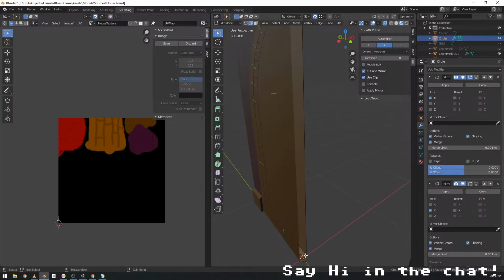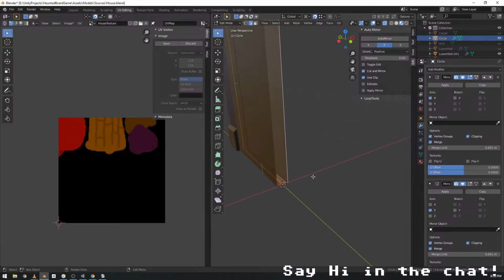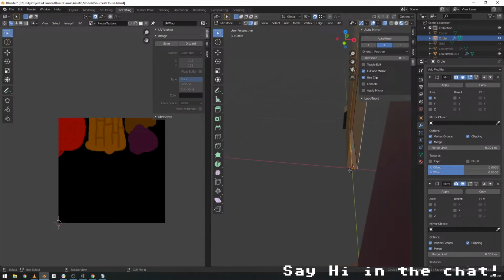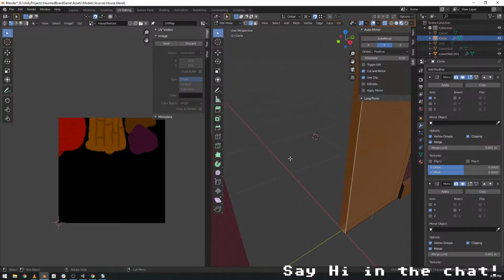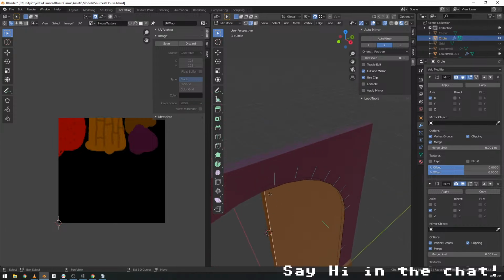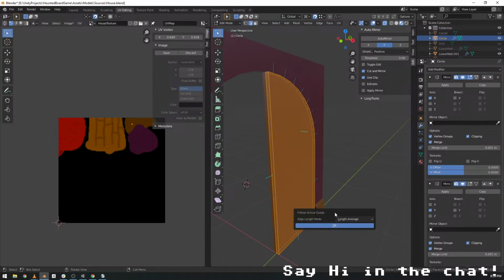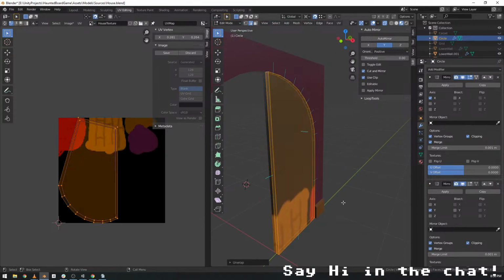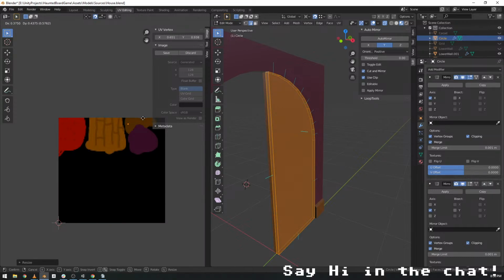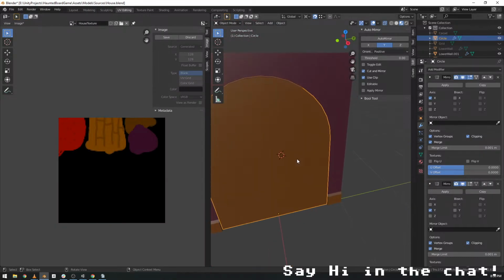So you can see there's no face here. So I'm just going to alt click the edge. Make sure that that one's selected. Ooh, all of it's selected. Get out of the way. Move, there you go. Get that guy, not that guy, that guy, and that guy. Throw a face on there. Let's just, nope, unwrap him. Scale him down to 0 again. There we go. Now we've got a nice door.